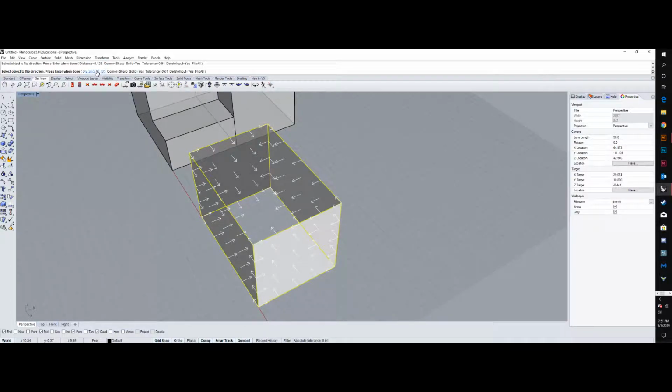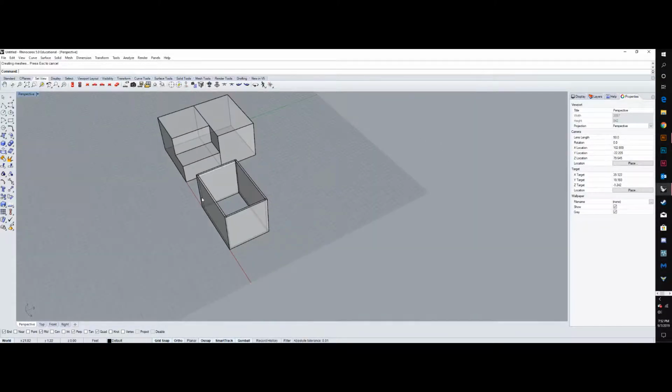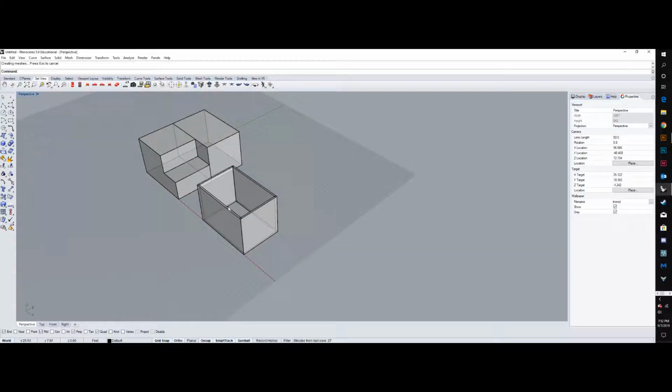Before I hit enter again, notice the distance is 0.125. That's probably 0.125 feet. I'm going to click on this, or type in the letter D and enter. I'm just going to click on it, and I'm going to change it to, let's say our walls want to be 4 inches thick. 4-inch sign, enter. Notice it's changed here. That's all we need to do, and hit enter. Now we have 4-inch thick walls at 10 feet high, and that, trust me, is a whole lot faster than doing each one individually and extruding them and then capping them.